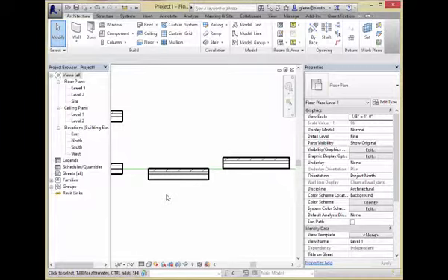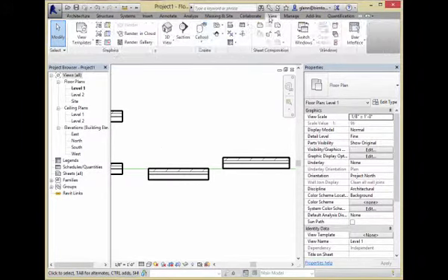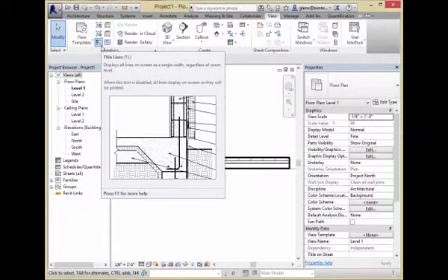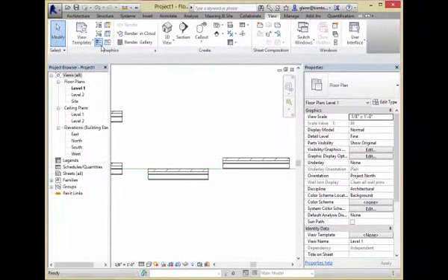If you do want to turn that off, go to the View tab, and you can just click, it's right over here. There's a thin line mode and a fat line mode. Thin lines will just thin them out. It just toggles between those two different modes. I like to do that sometimes because I can really see that the line surface does match.